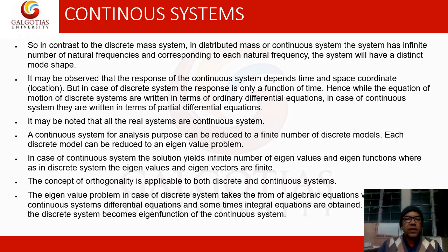It will be observed that the response of the continuous system is a function of both position and time. Hence, while the equations of motion of discrete mass systems are written in terms of ordinary differential equations, in the case of continuous systems they are written in terms of partial differential equations. It may be noted that a real system or continuous system can, for analysis purposes, be reduced to an infinite number of discrete models.